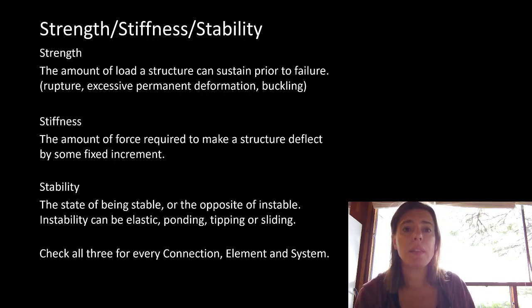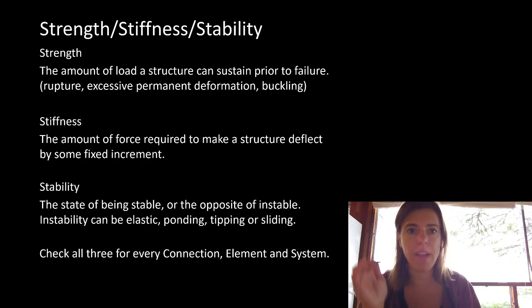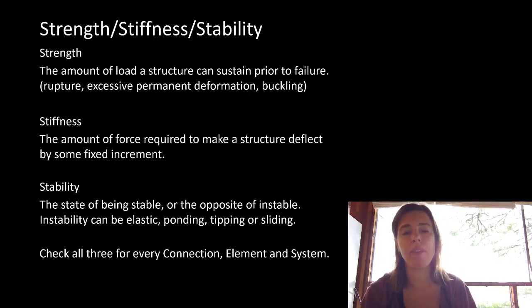And so these things are the things we check for every connection, every element, in every system. And those who took my course know that was a question on every exam. It was on several assignments, and it's just a thing that I wanted to drill into your head. Every connection, every element, every system needs to be strong enough, stiff enough, and stable.